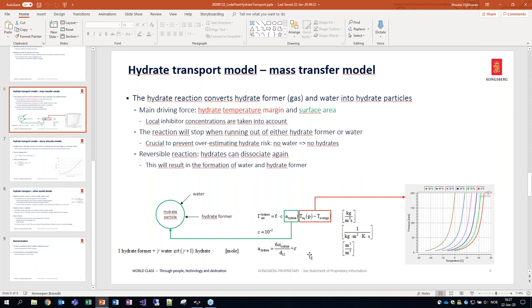So if you have a certain kind of oil, then you will end up in one situation, or maybe with gas condensates you will end up in the other situation. So you can't really design that. Yeah, so you need to do simulation. And then whether or not the hydrates end up in the oil or water phase, you can determine that in the lab.